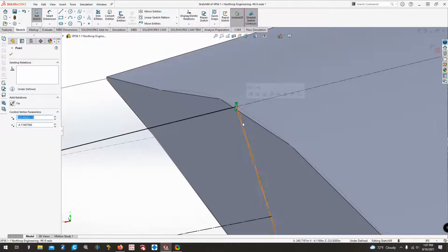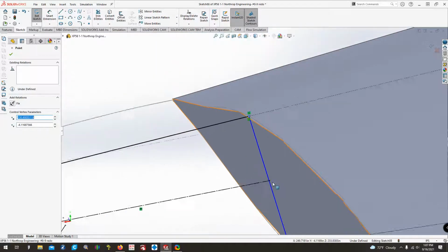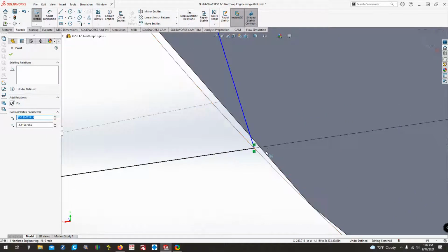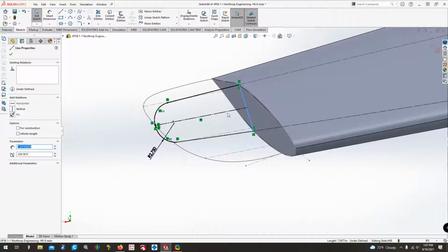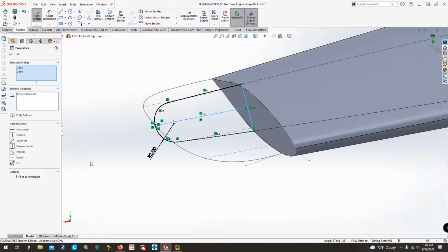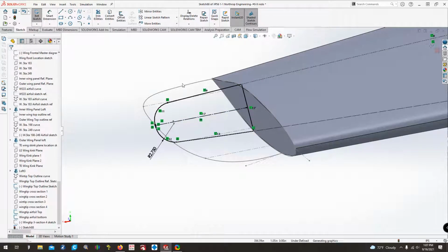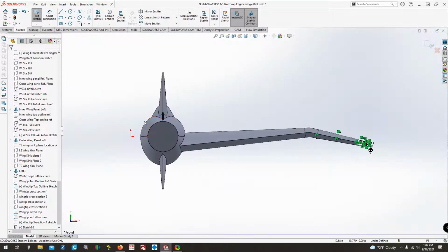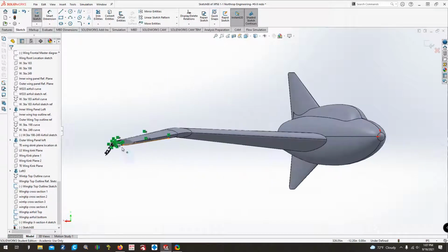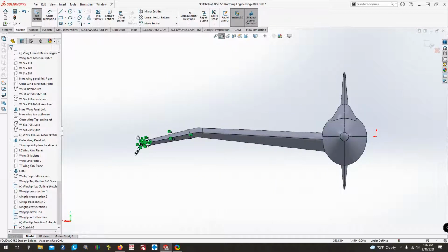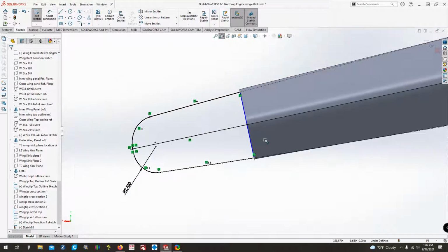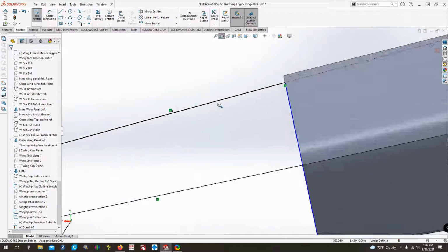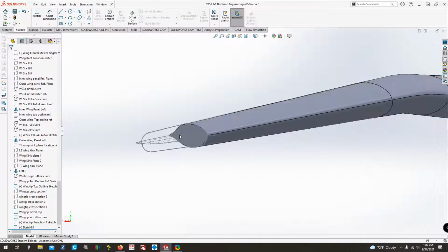I'm going to just drag it there. See, now it's coincident. For whatever reason, it just did not want to make it its own. And then let's see if this will go perpendicular. Yeah, but I kind of threw it off. It's no longer coincident there. So let's see here. See what it looks like from the front view. Yep, there we go. That's pretty much where we want it. Now we can exit out of cross section 3.